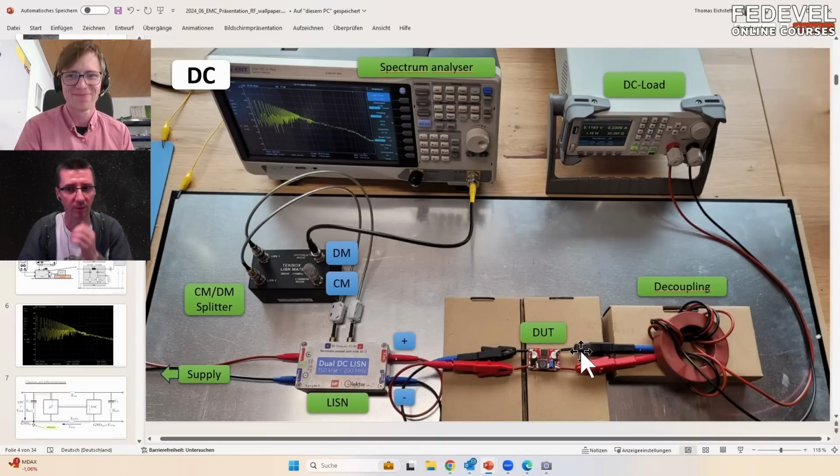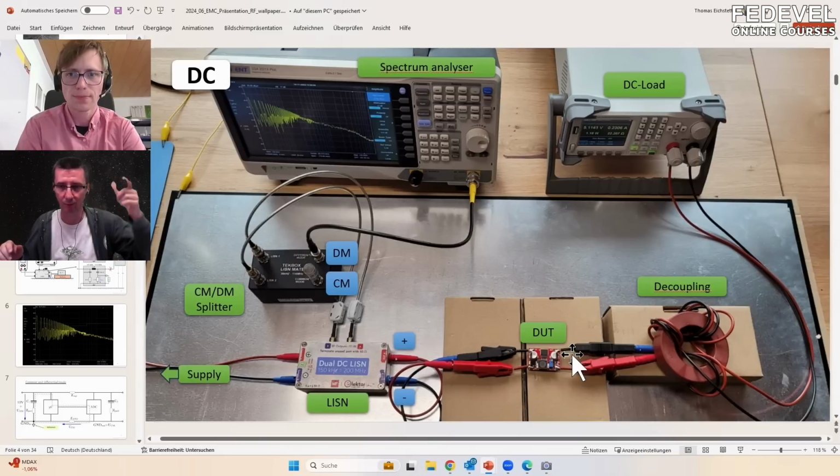And I think what we did, sometimes you get results from preliminary measurements in a real test house, and then you have some kind of absolute values. When you make this kind of setup, you should get the same kind of graph or waves, maybe relative to the measurements you got from the test house, so you know how much you need to reduce your noise.